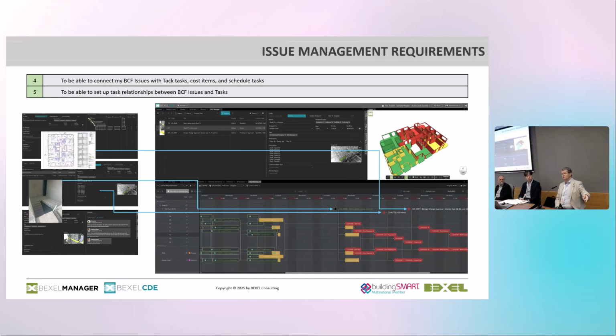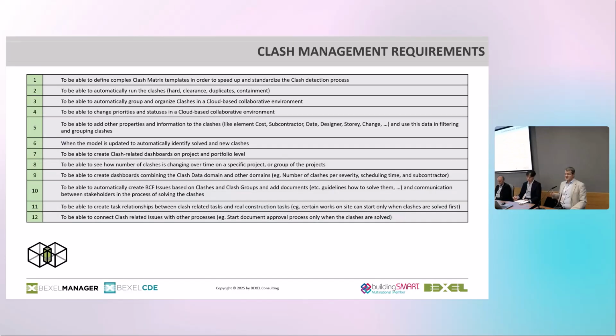If I can check what you said, if I can verify that the quantities are accurate, if I can see, as you can see in task planning, one of the key things is that I am assured that in this room, this week, or the first 3 days, only I will be there. So there are not going to be others. It shows us in line of balance or task planning style who is where, in which location, and when. And if I can be assured that this is so, then I can tell my guys to really focus on doing it efficiently, because everything else will be prepared for you.